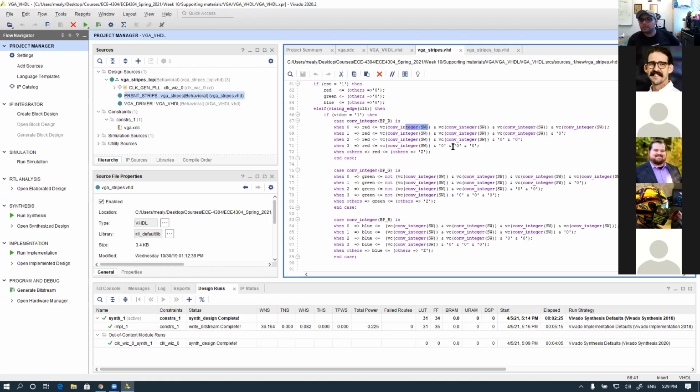Then we learned that we can also program the FPGA in another way, which is basically an SD card. We just need to change some of the jumper settings, and also power up the board. We can power it up still with the USB cable or just external power. And I did this in front of you. And then we have a full demonstration on the screen, as you can see.